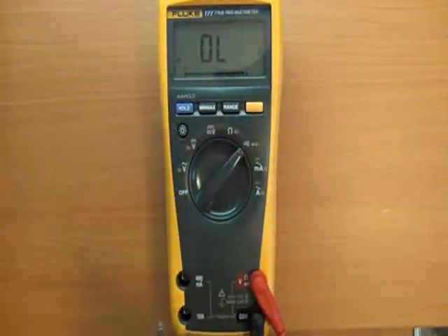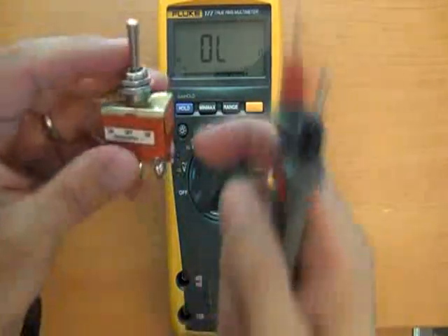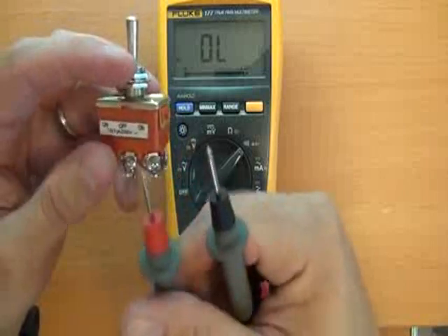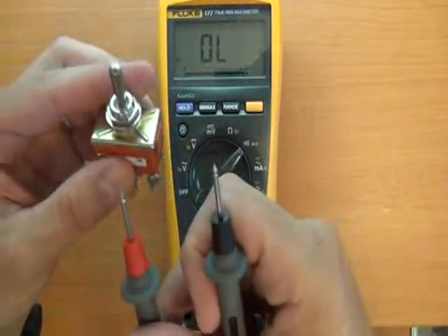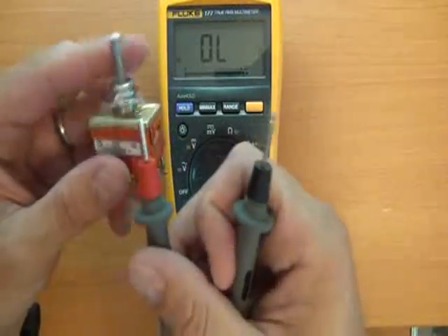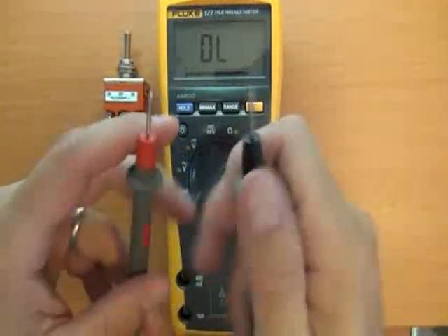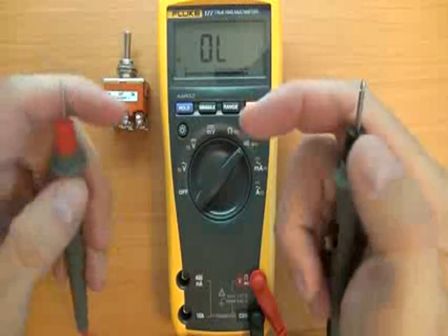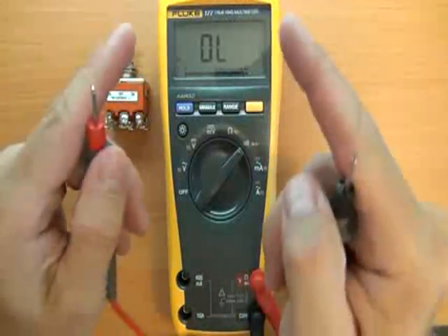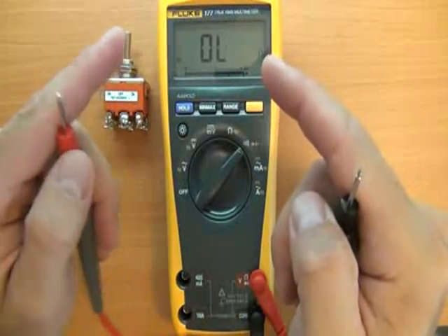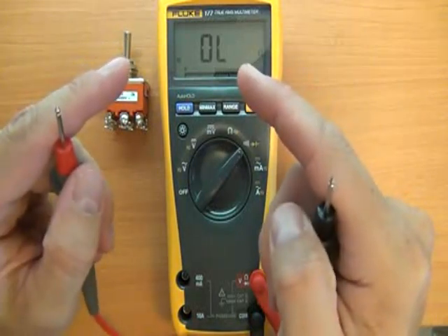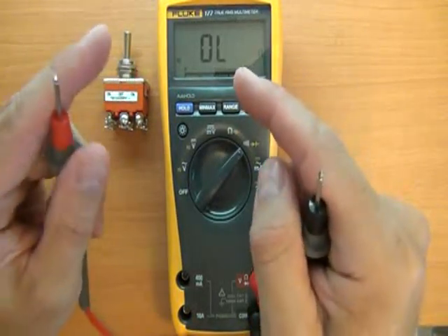So now when it comes to a circuit, as an example, I've got this switch here. Again, there could be 101 devices and bits and pieces that you can test for continuity. It could simply be a piece of wire, and you don't know if there's a break in a piece of electrical cord. Just remember what I said when I was showing you the analogy: always de-energize the circuits that you want to test continuity for.